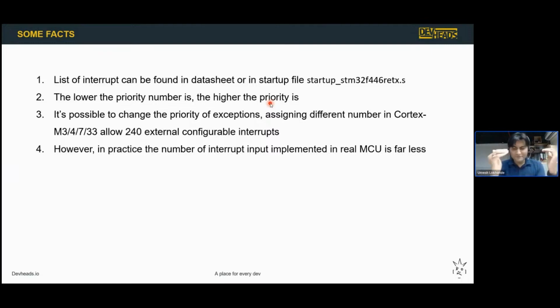But basically, if you are able to write your code without using an RTOS, not commercial, not even FreeRTOS, you keep the complexity of your code lower. Your code size would also be smaller, and you have direct access to the controller, right? So that's the advantage. Maybe we will speak about it someday in the office hours.